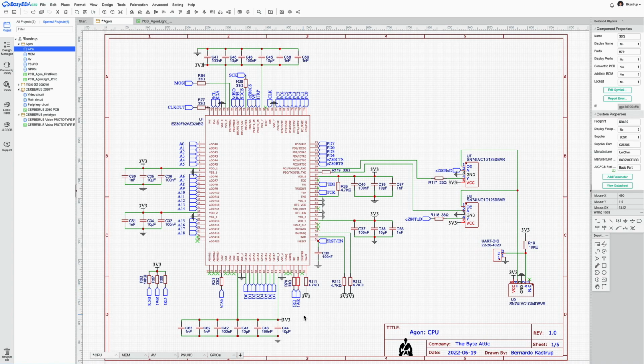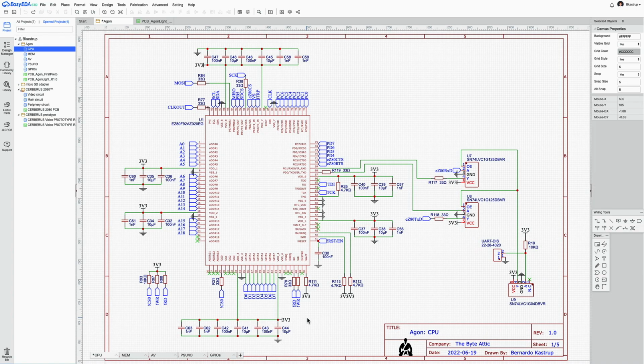If you have ringing on the signal that goes quite low, and this is the maximum of 3.3 volts, if it goes below 2, yeah, you have a problem. The memory may perform a write when it's not supposed to and contaminate its contents. And so that's why I use these resistors on the key control lines.